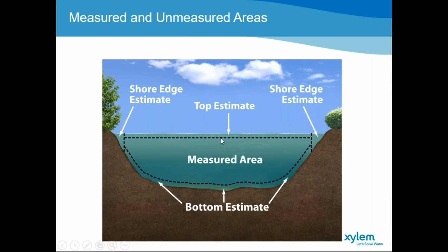The top edge estimate basically consists of the instrument drop or depth plus the blanking distance. That's the portion we can't measure, and that will be estimated. And then the bottom estimate default in RiverSurveyor Live is a 10% cutoff, and that is to prevent any side lobe interference from impacting the actual measurements itself.